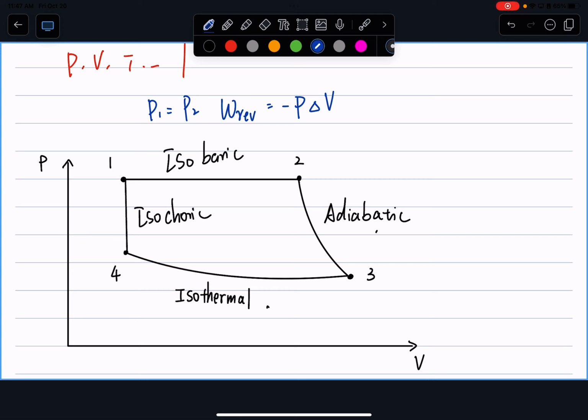For the heat here, it is an isobaric process at constant pressure. So what we have is Q_P. Remember what Q_P equals? Delta H. Right, so we went over that derivation of what Q_P looks like. And if we know it is an ideal gas, you can also calculate the change of internal energy and consequently get what Q_P is. And we have, well, dS